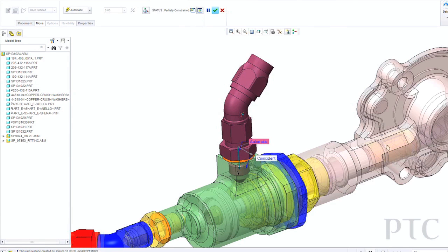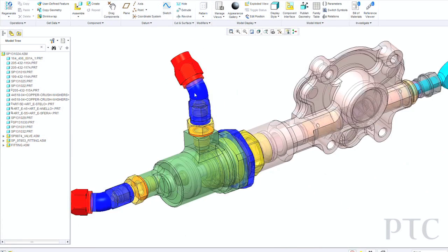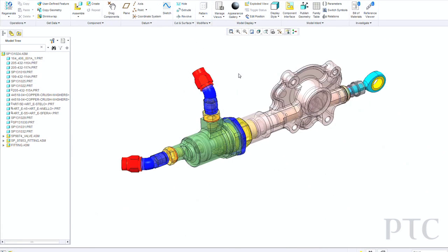And we'll automatically recognize, hey, you pick one cylindrical surface, you pick another, we've snapped to that. Then I just picked one planar surface. As soon as I drag up and down, because that's the only degree of freedom left, the system's smart enough to snap at each surface that's within a certain tolerance vertically as that thing is assembled to that part. So it makes it nice for improving how easy it is to assemble components.